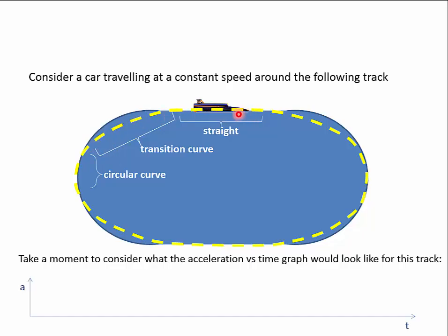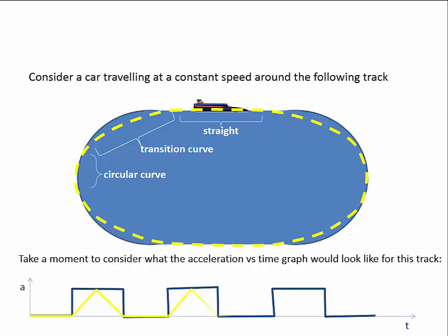So what we end up with is a more gradual increase in curvature, travel around the circular curve, and then a decrease in curvature. Rather than having a situation where the jerk is very high, we can now modify that so that the driver experiences a much smoother jerk, a much smoother jolt, and not that rapid change in acceleration.